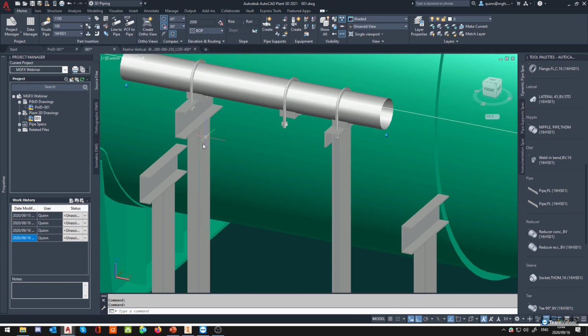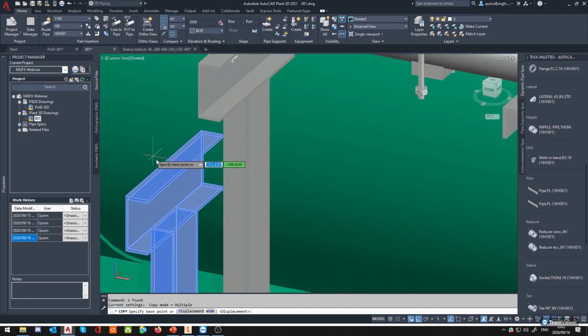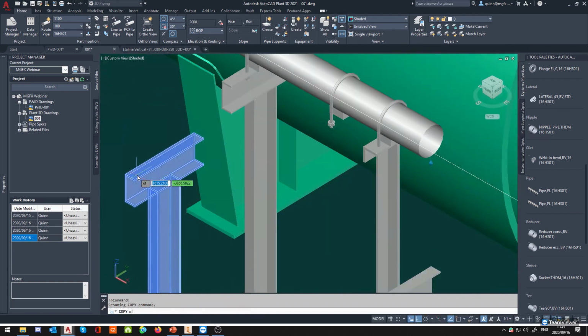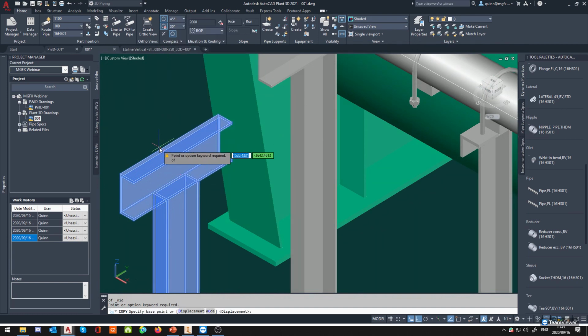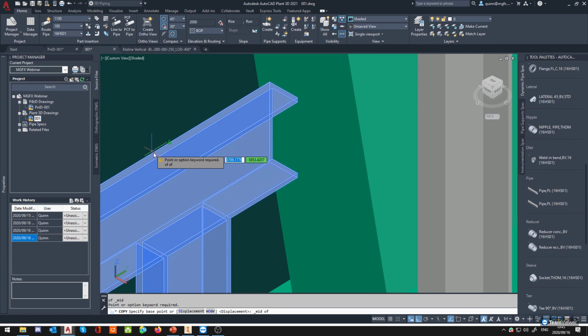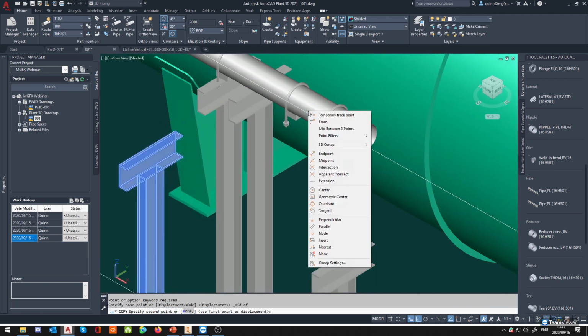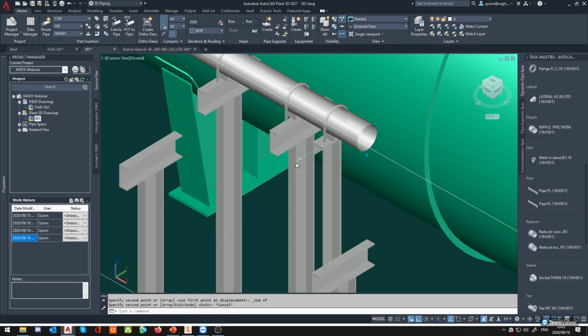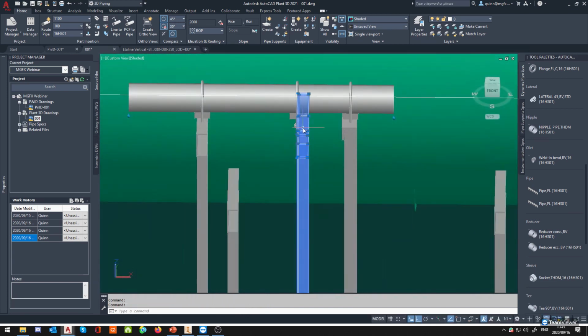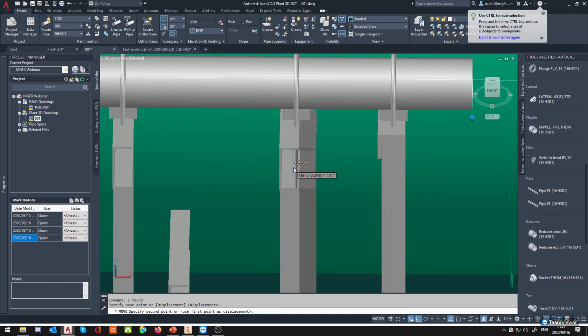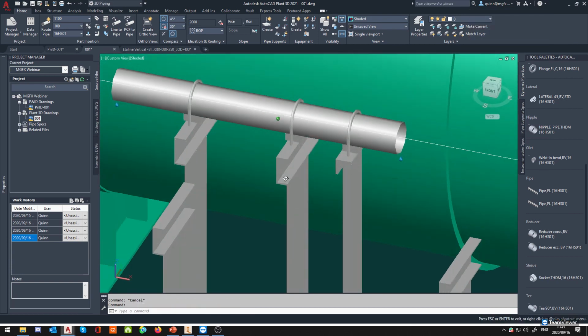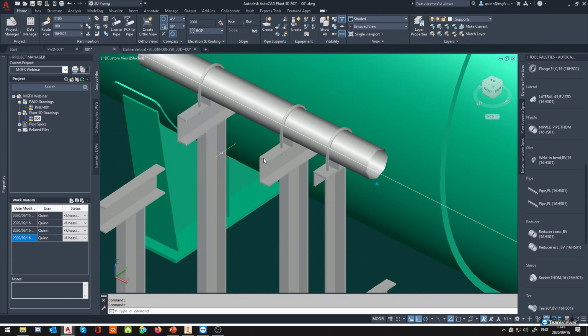This is where it gets a little bit more finicky, and it's more about trying to get as close as possible. But what you could do is then use your other piece of steelwork, just a normal piece of 3D modeling that you've done, or otherwise intelligent, depending. It can get a little bit tricky. Go to our midpoint, if I can grab it. Let's see. This node. And voila, on there. I know that this is a 200, so if I move it back by about, let's say, 40, that should be fine. And now you can see basically what I built over there.